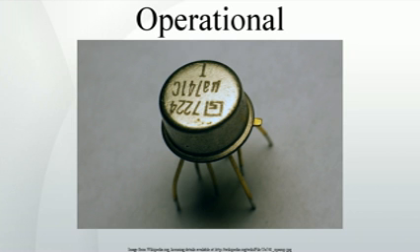Voltage amplifier. Quiescent currents in Q16 and Q19 are set by the current mirror Q12/Q13, which is running at 1 mA. Through some mechanism, the collector current in Q19 tracks that standing current.